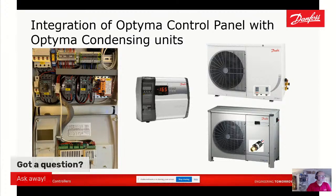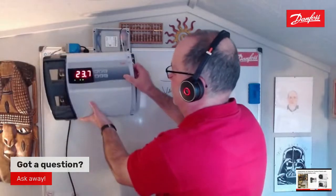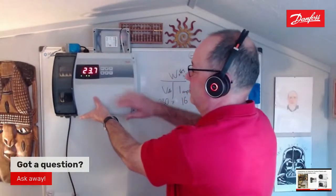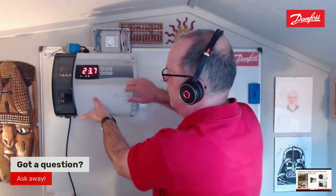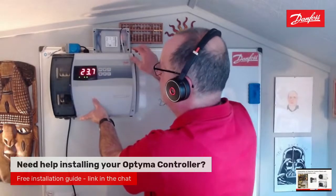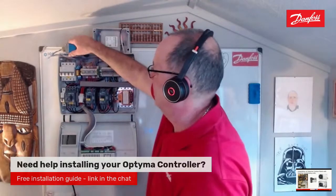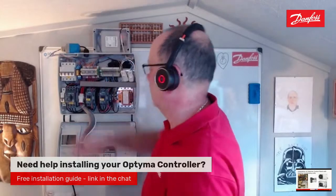Again, integration of the control panel with the Optymas. What I've done here is rig up a three-phase version, so we've got a little bit more inside. I've not got a condensing unit down here, which is a shame, but we've got our control panel. Flipping the lid up, that's what the customer sees: a nice big temperature display and the icons. We know our evaporator fans are running, and we've got refrigeration up there, operating via a pump down, because my little solenoid valve up here is working away.